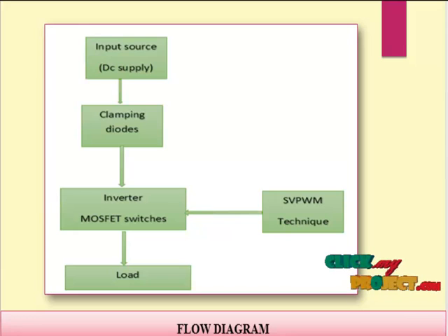This design can create high power quality for a given number of semiconductor devices than the fundamental topologies alone, due to a multiplying effect of the number of levels. The space vector pulse width modulation technique gives better pulses in the low frequency range. The switches also withstand the high frequency range and the switching losses are reduced. Compared to the classic 4 level topologies, it has fewer components and less complexity, and this is the flow diagram of our product. Here this is the input source.